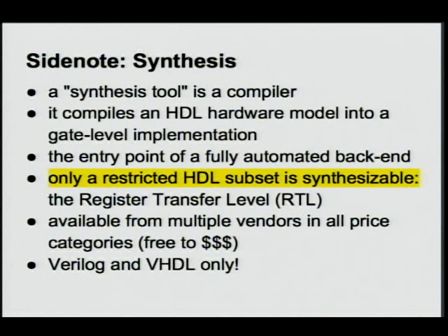Okay? Now, synthesis is available from multiple vendors, from FPGA vendors, EDA vendors, and in all kinds of price ranges. Free, and also very expensive and very good. But, as you can imagine, it's Verilog and VHDL only. So you see the problem with MyHDL. I can have a very good HDL, perhaps, but if I don't have a link to synthesis, I don't have anything practical.